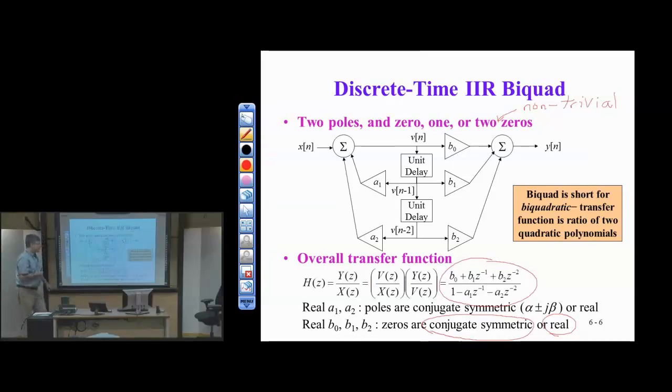Okay, so now this is our second order section, and a couple interesting things here: again, B0, B1, B2, and A1 and A2 are all real valued. You'll notice that there is no A0 separately mentioned. The A0 here is typically normalized to 1.